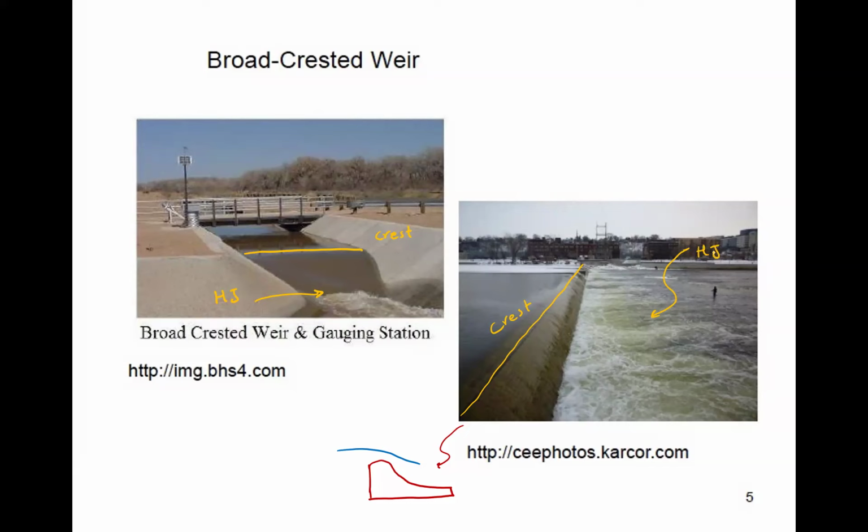When you create supercritical flow, likely you'll have a hydraulic jump to convert it back to subcritical somewhere. And if it's designed, you want to have a hydraulic jump. So this is a relatively small weir. It might be used for water level control. That's very common to bring the water level up.